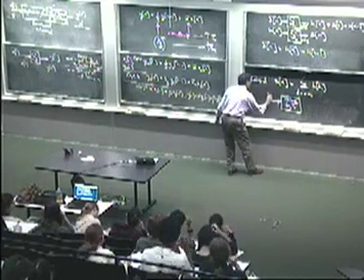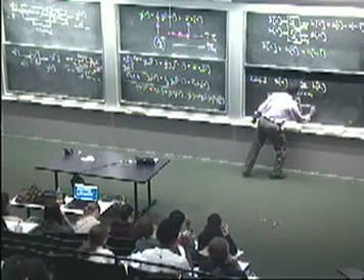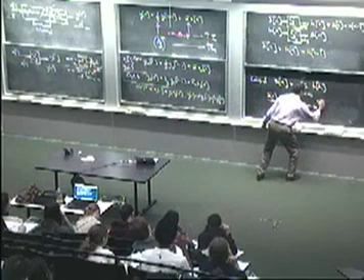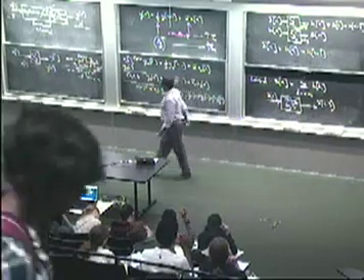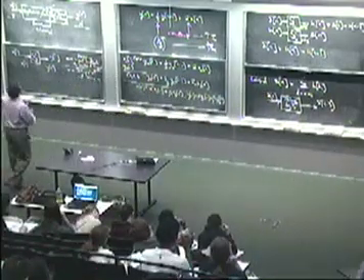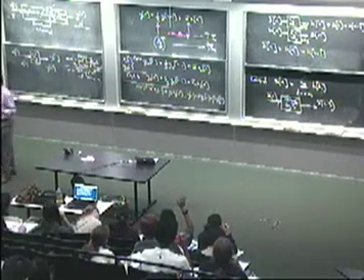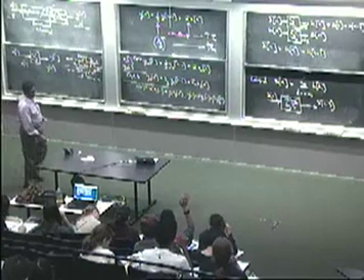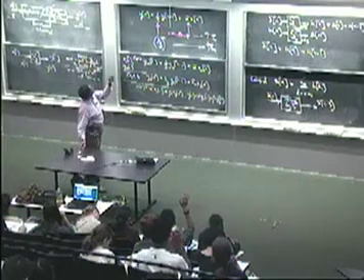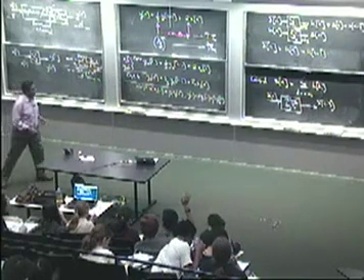Because we put in a unit sample function, and what came out, if you look at it, was actually delta of n minus 3. It was a unit sample function delayed by 3 steps. The height is unchanged, right? The height is still 1. So this must be a delay by 3 system we're looking at. And sure, if we put in a unit step, we're going to get a response that's just the step delayed by 3. Okay?